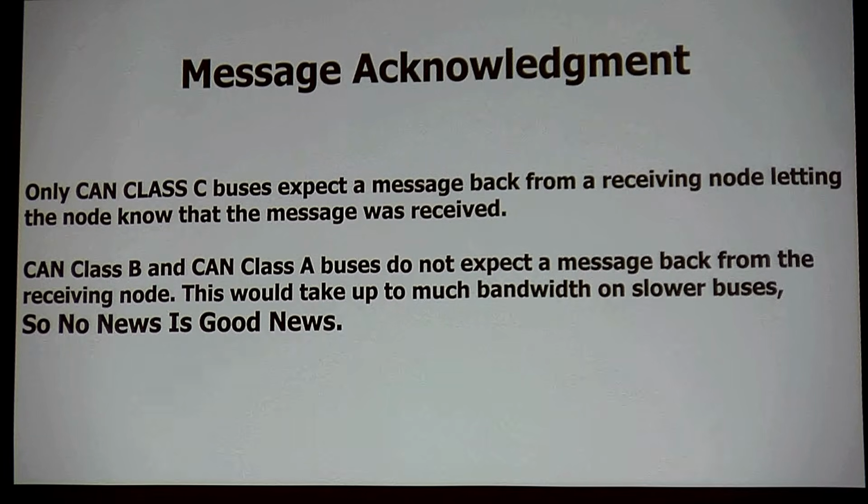And you're wondering how that could happen. Well, the reason that can happen is because there's no acknowledgement and there is no frame for me to get back a message. So you could have a DIM, something like a driver information module, the dash, and the dash is totally dead, and you're trying to figure out what's wrong with it, and there's no codes, and none of the other modules on the system are set with a code, because in CAN, we shoot the messenger.